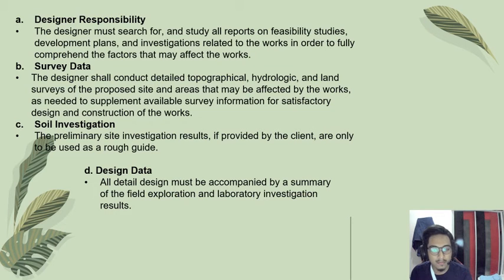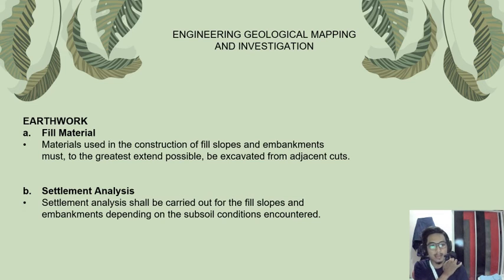of the work. For the soil investigation, the preliminary site investigation result provided by the client is only to be used as a rough guide. For the design data, all detailed design must be accompanied by a summary of the field exploration and laboratory investigation result. For the earthwork, fill material used in the construction of fill slopes and embankments must, to the greatest extent possible, be excavated from adjacent cuts.